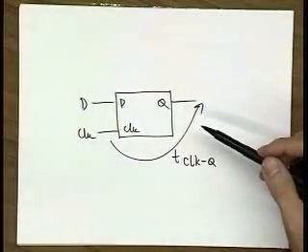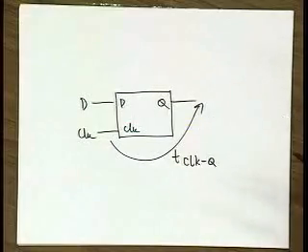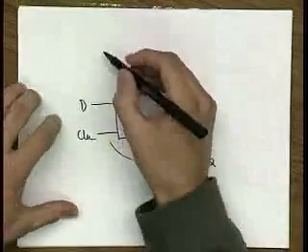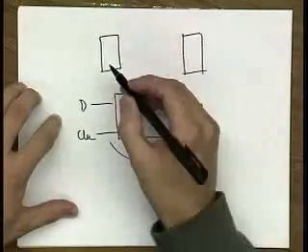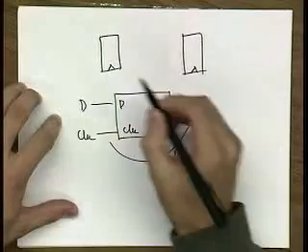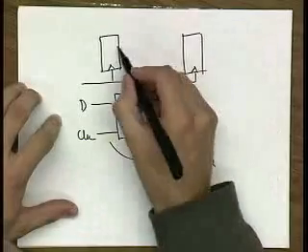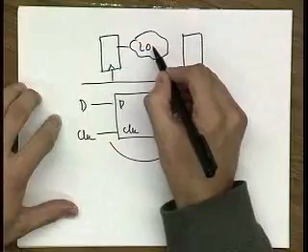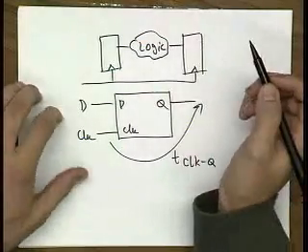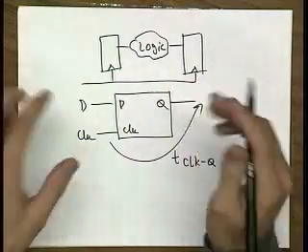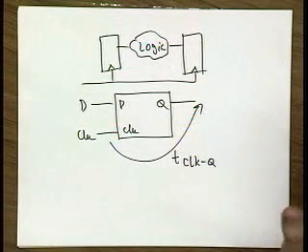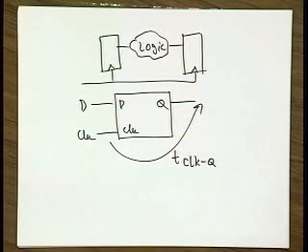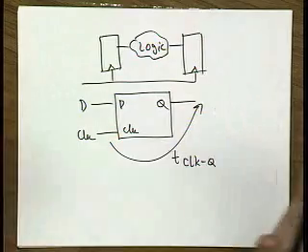The reason you want to do this, as we will see later on, is, let me draw the big picture to understand the context. Let's assume that this is your pipeline stage. You have a clock, and then a cloud of logic in between. To determine the cycle time for your design, how fast you can clock it, you ideally want to understand the critical path, how much you can squeeze your timing to achieve the highest performance.